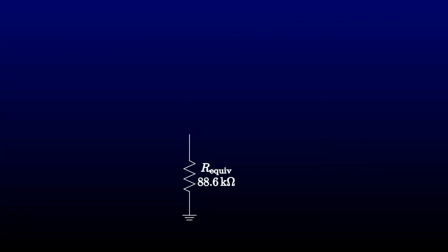I actually don't like this result very much. It's a little short of 9 times the source impedance. I usually like a much higher impedance coming in. Put a pin in that. We're not done with emitter-follower biasing. But for the moment, we'll keep going with what we have.